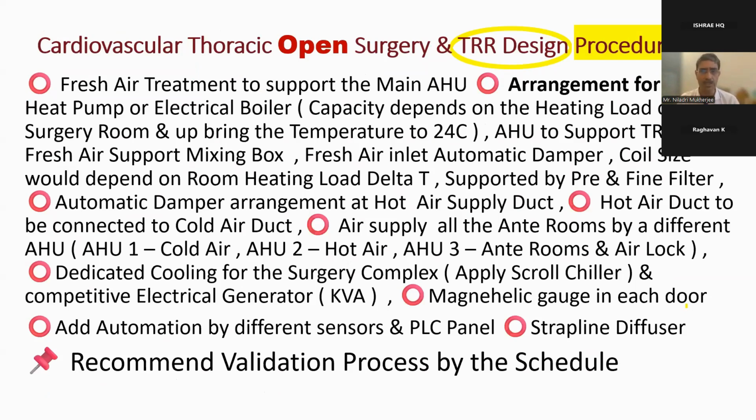surgery area and post-surgery area. There is a heat pump and electrical boiler. Capacity depends on the heating. The AHU supports the fresh air and the mixing box. Fresh air inlet automatic damper. Automatic damper arrangement at the hot air supply, to be connected with the hot air. Anyhow, I will explain this in the diagram. Here actually one main important thing: they apply a scroll chiller. Why are they recommending a scroll chiller?